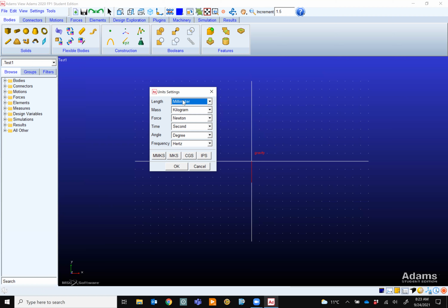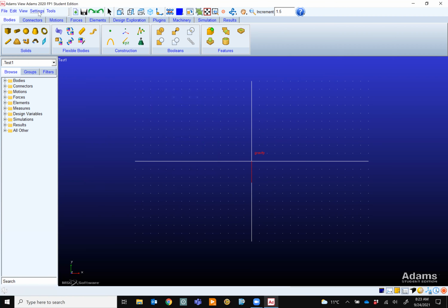Then you're going to have your input for a motor, for example, where you want the torque to be in Newton meter, but it is in Newton millimeter. You enter it as 300 Newton meter, but since you changed your unit here to millimeter, you're going to mess up. So be consistent. That's my advice. However, you can change your unit.